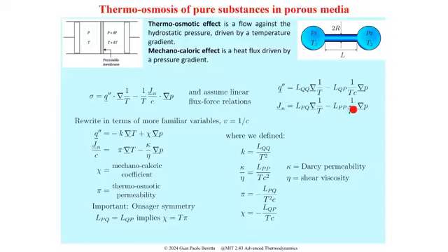So you can rewrite these expressions, because usually what we do is be careful in using the entropic degrees of disequilibrium, so that we know that that's where the Onsager reciprocity applies, and so I can safely say that these coefficients L_QP is equal to L_PQ.